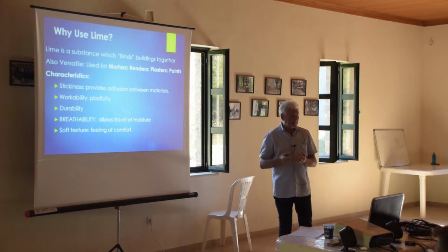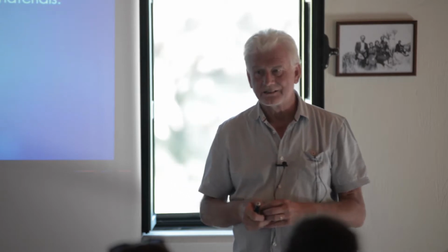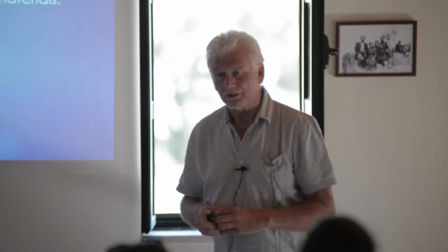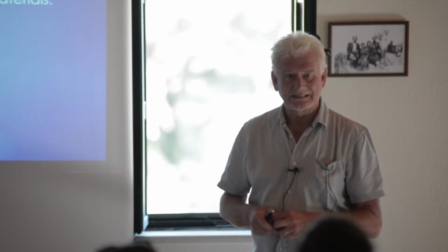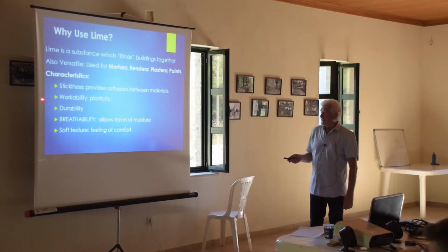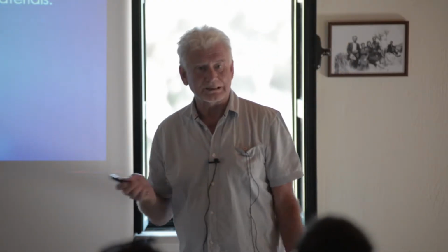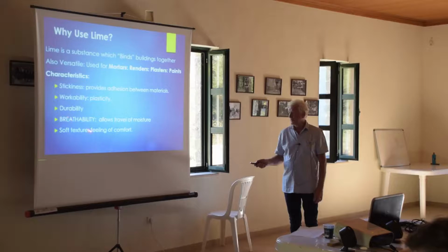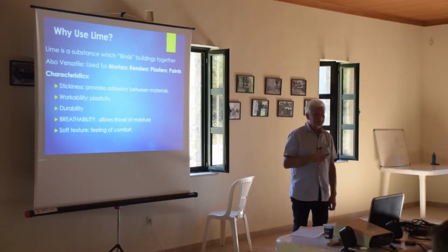And it lasts in the way that cement does not. If we mix cement today, you have to use it today. If we mix lime mortar or lime render today, I can use it in a year's time, provided I protect it. Okay? It's very durable. You've seen it clearly from the age of the buildings which are still standing, which have resisted over the years. And we come to this. If you remember anything at all about what I say tonight, remember that.